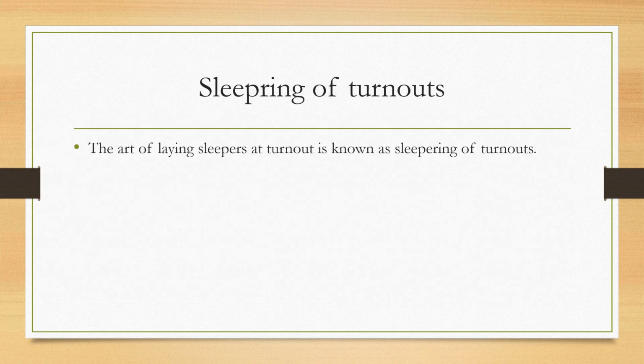Sleepering of turnouts. The art of laying sleepers at turnout is known as sleepering of turnout. Two methods used for sleepering of turnouts: by through sleepers, by interplaced sleepers.